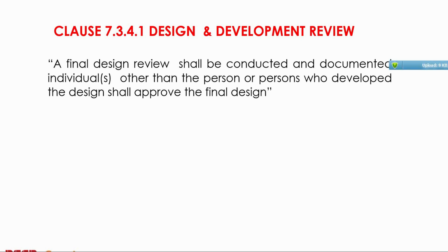I hope you're familiar with this term, fag packet, cigarette packet engineering. It is a term often used where the design engineer does not fully document his thinking and product development stages. He thinks that documenting the finished product characteristics is enough. Often the same process will be gone through again in subsequent designs, whereas if the thinking and the rationale had been documented on why the design might have been abandoned or failed, it would have prevented the process having to be repeated again.